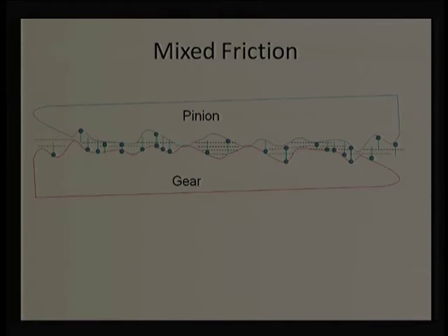So, this is what a mixed lubricant is; it was more like dry lubrication with a solid lubricant. If I say a more appropriate word, solid lubricant can also be treated as a boundary lubricant. They are making a boundary layer. But when we use a liquid lubricant along with a solid lubricant, then the situation turns out to be mixed lubrication. What is the reason for that? Here the load carrying capacity will be shared by liquid lubricant, solid lubricant, metal to metal contact and full film lubricants. So, all four domains, all four mechanisms of lubrication will be there.